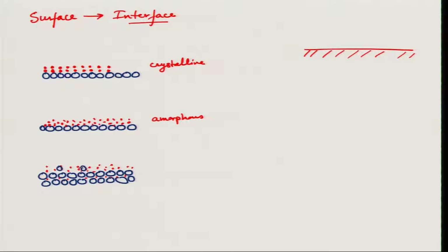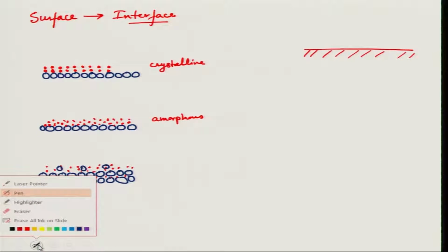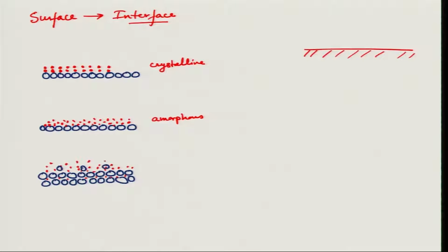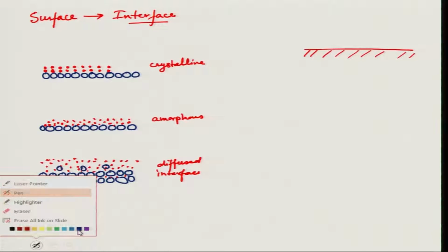Some atoms might diffuse into the thin film also. So, this will not have a sharp boundary, but due to interdiffusion it will have a diffused interface. These types of thin films will have better adherence to the surface, because they are interdiffusing and mixing with the material of the substrate, but they are still separate elements. They can also form a compound.